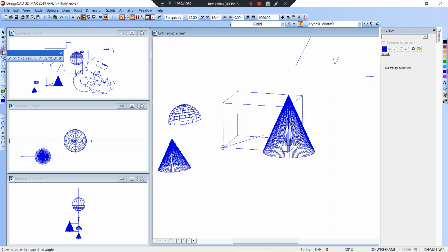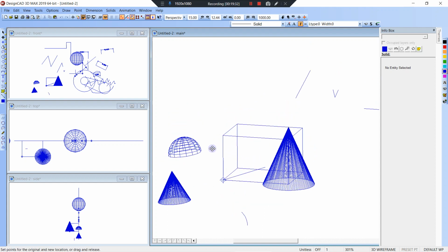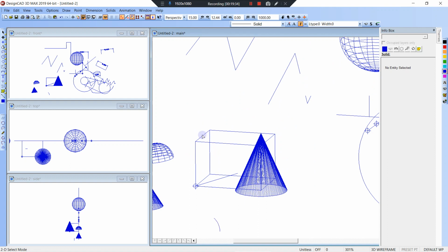Arcs. So there's different types of arcs. Thought they would highlight. I have to put it there, and that's just a plain old arc at 50 degrees. Enter. So if you were in 2D and you wanted to draw that there, you could do the same command. I just hit P for pan, and then we want to go to the arc again.